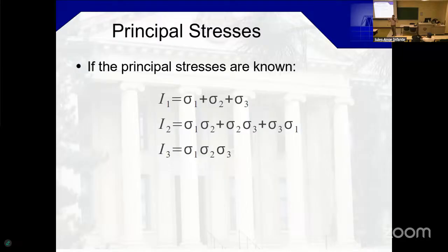What you want to do is play with numbers in a certain range of values, play with rotations. Start with a given stress matrix, rotate it in a given direction with the equation we saw with the transpose, and now do the analysis of stress invariance with rounded values to different degrees of those matrices. And see the agreement of the stress invariance. See how much they start disagreeing, even starting with equal, identical states of stress.